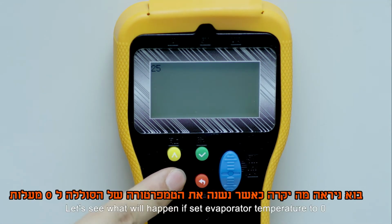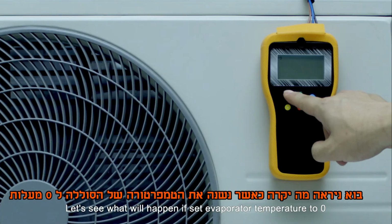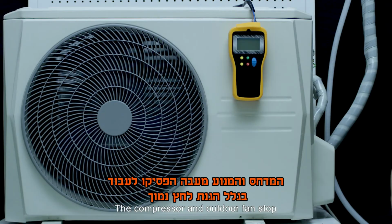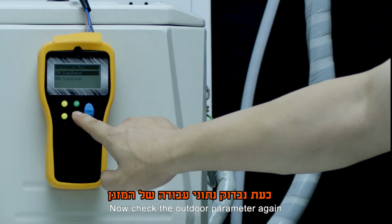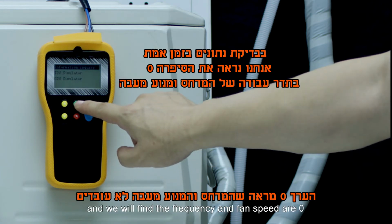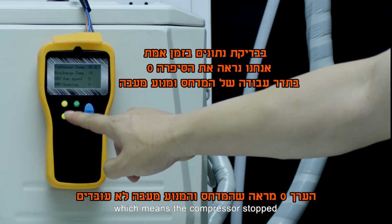Let's see what will happen if set evaporator temperature to 0. The compressor and outdoor fan stop because protection program of low evaporator temperature is active. Now check the outdoor parameter again, and we will find the frequency and fan speed are 0, which means the compressor stopped.